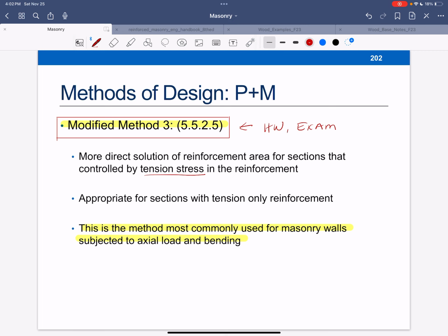And let me talk a little bit about where the reinforcement goes in these things. So let's say I've got my block, here's another block, and here's another block. If I've got the lateral load coming from this direction, the tensile steel is basically concentrated here, right? So I can have some steel in these different voids towards the edge. If the wind or seismic comes from this direction, I need it over here. So what you'll see in those walls, if I draw the wall section, you'll see reinforcement kind of clustered towards the edges. That's what's true in concrete shear walls as well. Or you can go ahead and have it all along.